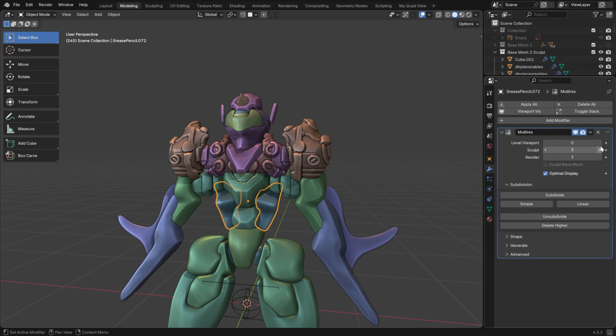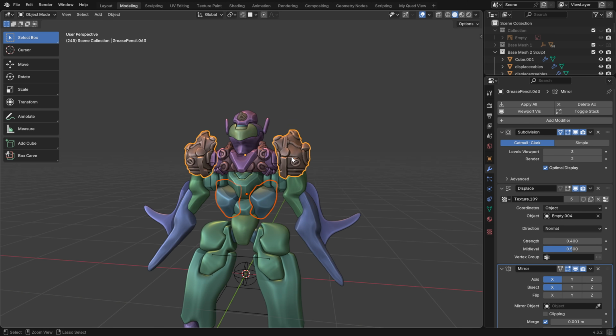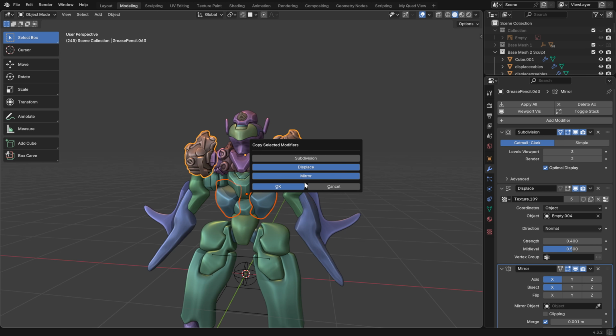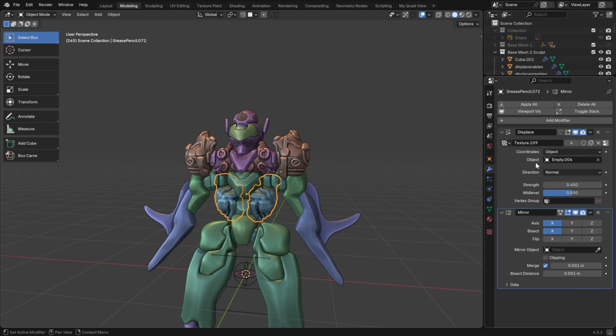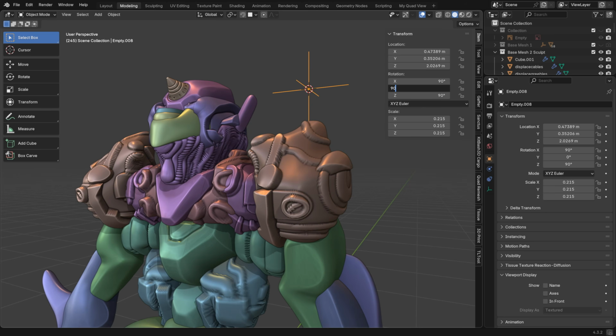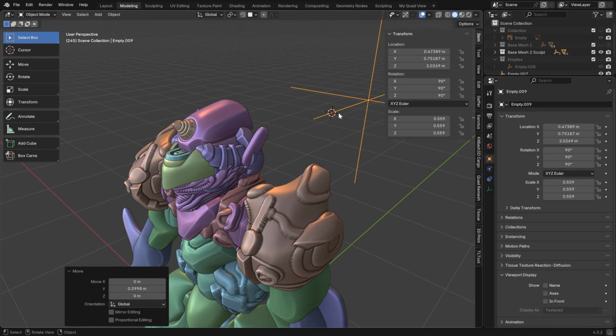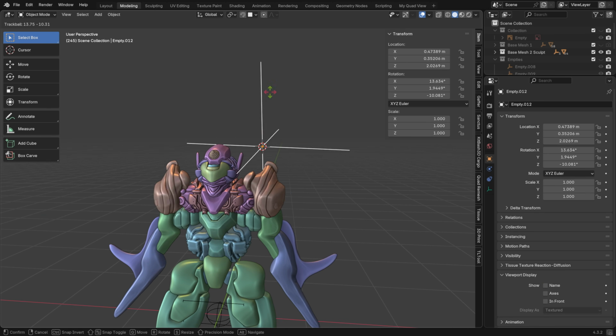Here you again see how different the base mesh and the multires result can be. I applied the multires modifier with a low resolution so that I have a good base mesh for the tiling displacement to do its thing on. Of course, this is all explained in much more detail in my video course, and the files for that are included there as well. Here I'm using a different tiling displacement map, this one with cables. By controlling the displacement with empties, you can quickly experiment.